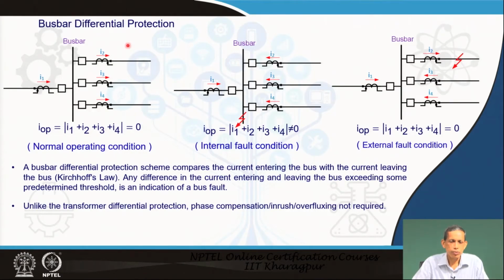Widely used for bus bar protection is the differential protection. For that perspective, we have already learned about transformer protection, and in earlier lectures we learned how transmission line protection can be done. In bus bar protection, we do not have issues like inrush current, overfluxing or phase compensation, so it is pretty simple and based on simple KCL applications